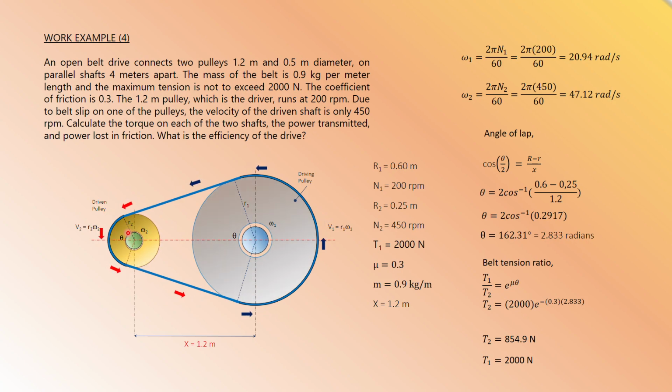To produce a torque on a pulley, you must have tangential force multiplied by radius, remember. So the tangential force here is T1 multiplied by the radius, R2 or R1, up to you. Here you will have T2, the other force, multiplied by this radius, giving you another torque.